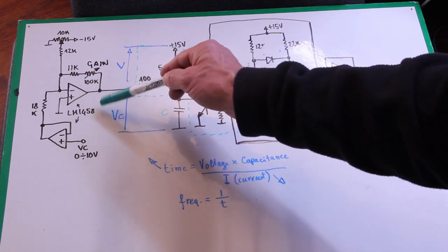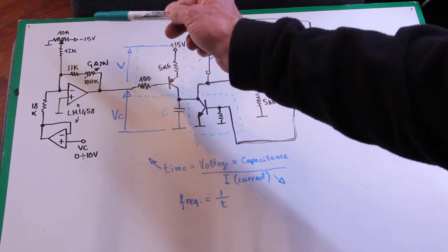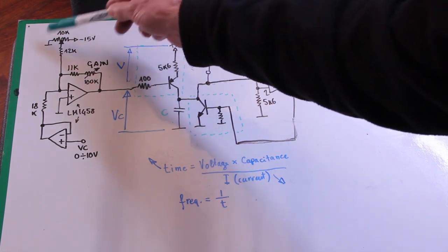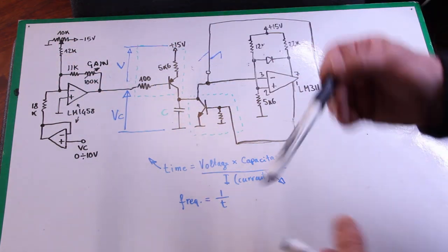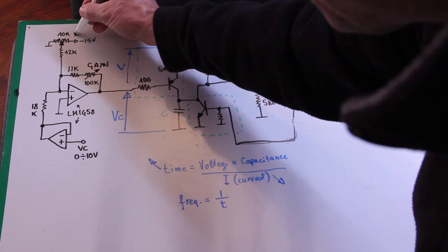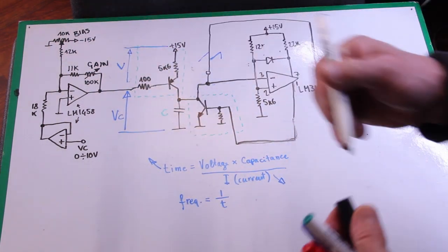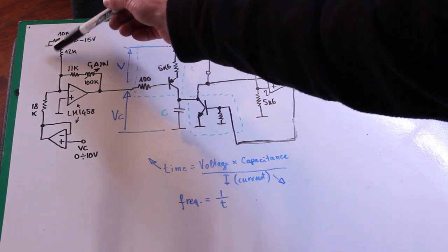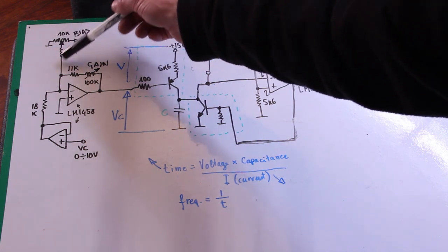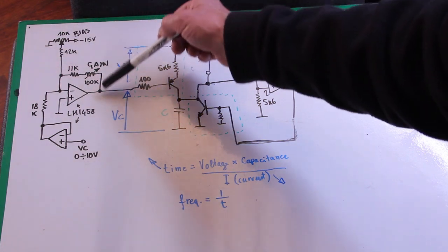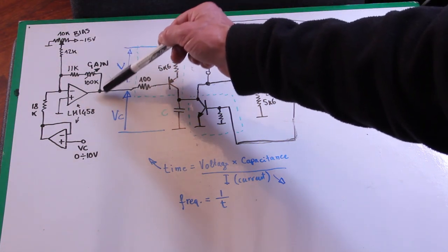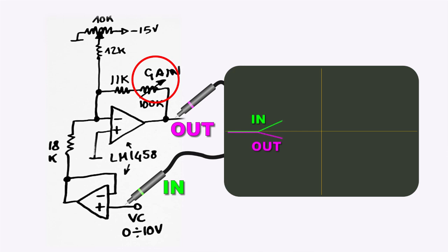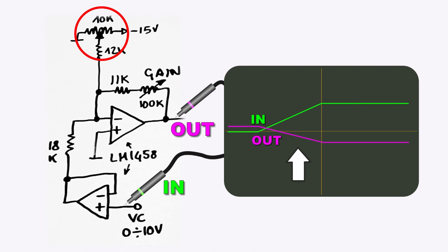And to compensate for the fact that it goes negative, we have here a bias control that is used to correct the voltage by feeding a negative current through this resistor and moving the whole voltage excursion, the whole voltage range, from 0 to negative to 0 to positive.